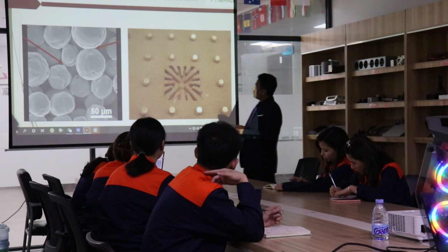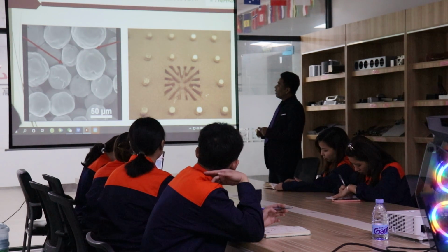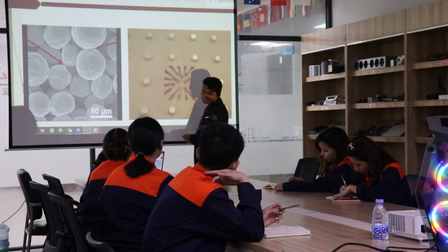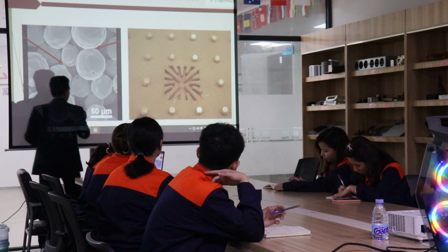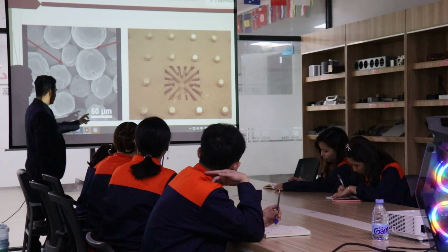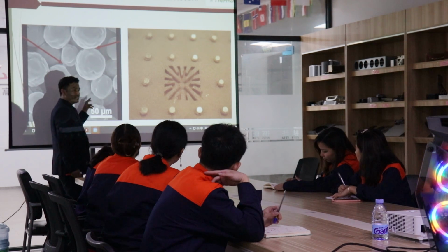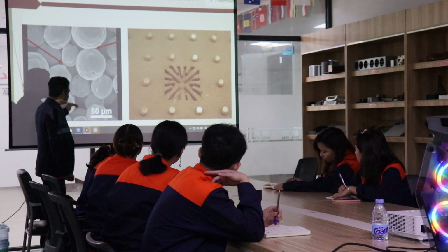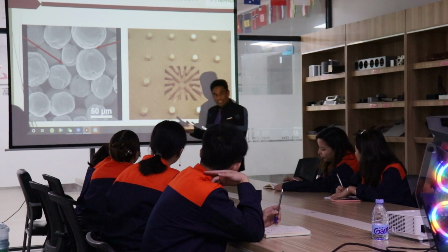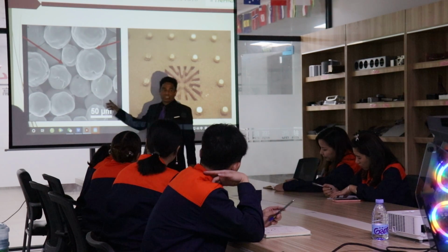And next, the photography of sintered wick materials. That is the wick, inside the wick, the pore, and this is the size of the pore, 50 micrometer. Based on this size, the technology will change. The working fluid, the working phase change, and everything will depend on pore size.